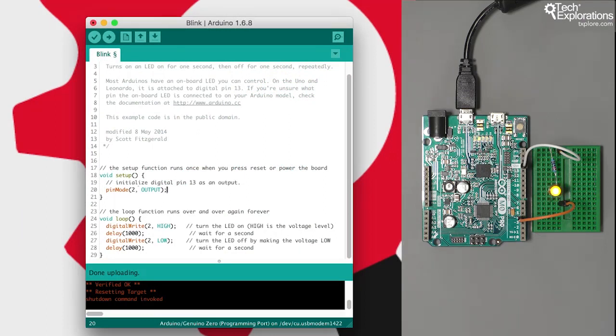So when you are utilizing digital pin 2 in your sketch, digital pin 4 on the hardware actually responds instead of 2. So I'll show you how to fix this situation in your Arduino.cc IDE next.